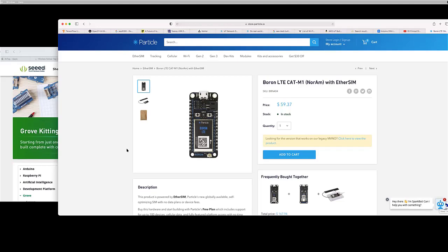But from a proof of concept point of view, if you're a consultant, you're going in and you're trying to do OEE calculations. What does that mean? OEE is availability times performance times quality. In order to get the performance, you need the production rate. How many parts per minute? How many parts per hour? And if you can't count how many parts per hour, you're out of luck on that calculation.